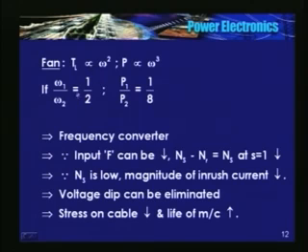if you try to reduce the speed of rotation itself, you are able to regulate the air in the case of a fan, or the discharge in the case of a pump. Then what happens to the input? See here, power input, suppose the ratio of the two speeds, omega 1 to omega 2, is 0.5. The ratio of power is 1/8.